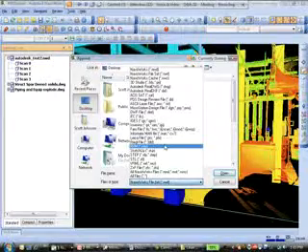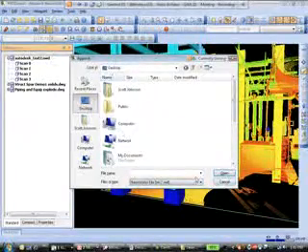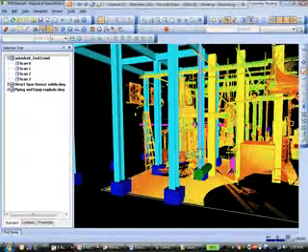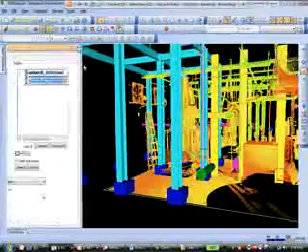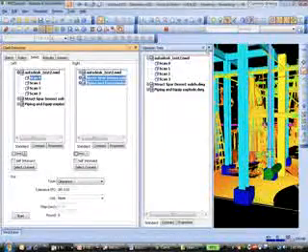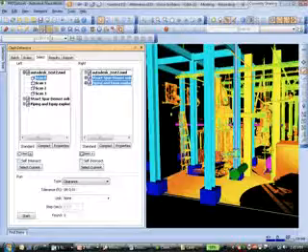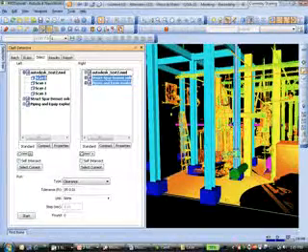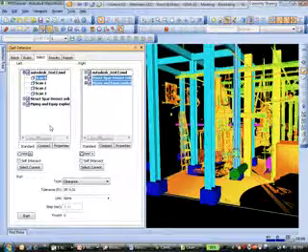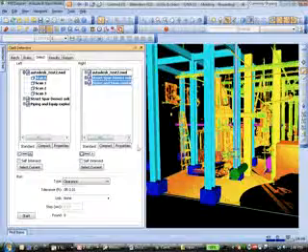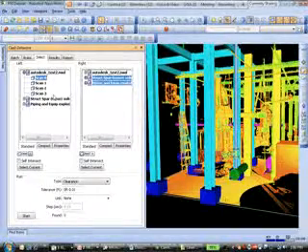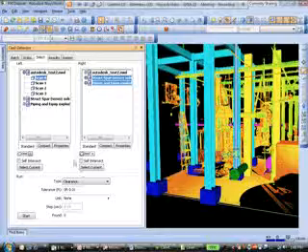And then when I go into my clash detection mode, typically one of the best ways of managing clashes is to take the elements and create a search or selection set so that we're grouping them down by either discipline, location, material, any number of different events. When I open my clash detection model, now I have the different models. So I could have an AutoCAD file, I could have my scan file, I could have Revit files, I could have IFC files from maybe a third-party application. All these different file formats we can now select, and then we can run a series of different clashes.